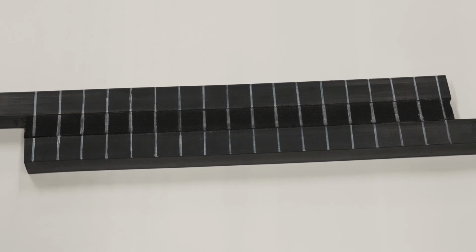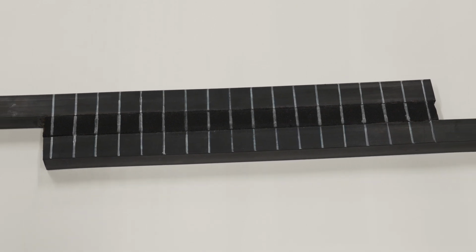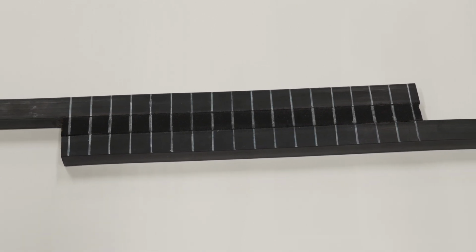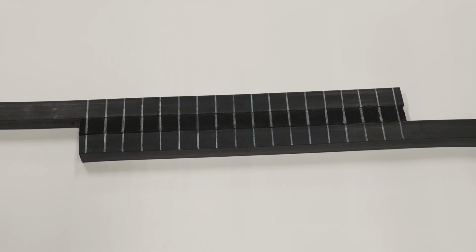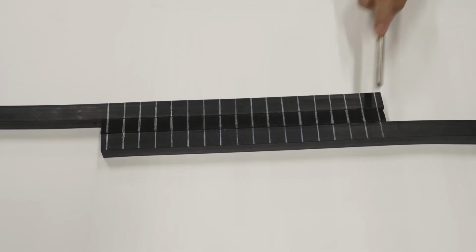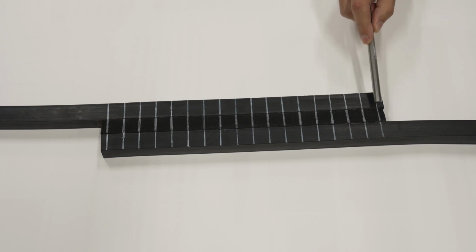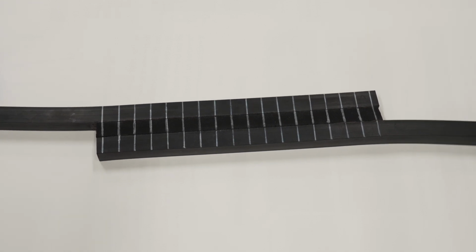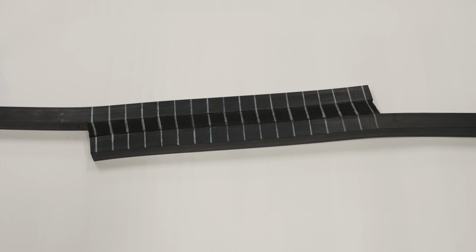To illustrate the concept of differential straining, we have here a rubber model. For the substrates, we have hard rubber, and for the adhesive, a foam. At this stage, the joint is not loaded, so there is no deformation in the adhesive and no deformation in the adherent. But then, if we load the joint, clearly there are deformations, especially in the adhesive, but not everywhere.